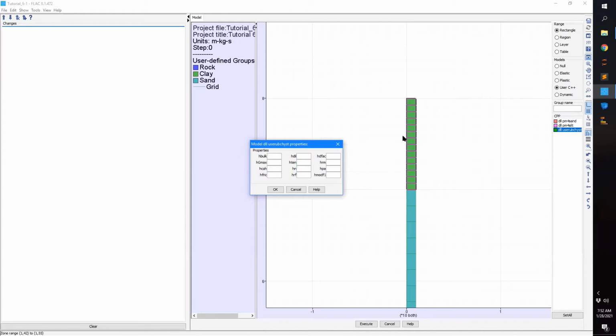Now, one important thing to note, and this is an important distinction to what we did for the Mohr-Coulomb model, is that this bulk modulus and this shear modulus are not intended to be representative of, say, the E50 value, but instead they're intended to be representative of the value that you would, for instance, determine from a geophysical investigation. The reason being is that the UBCHYST model then degrades that particular stiffness. And so we want to ensure that we are starting with the correct value.